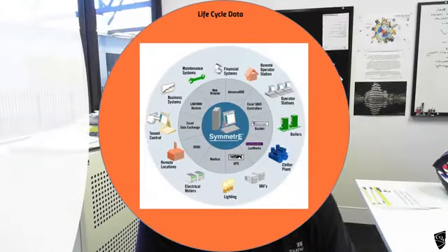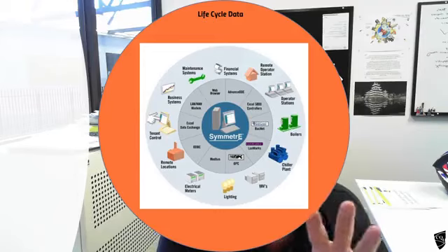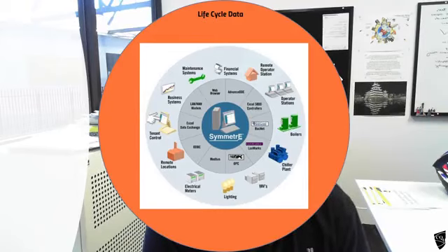Building management systems. Now this is what exists before building information management came along, and building information management is slowly absorbing these building management systems. But a building management system, it's got maintenance systems recording what needs doing and when it was done and who did it and how much. Financial systems, it can be operated remotely, so you can look at other sites. There's operator stations which might only be in the maintenance room or in the air conditioning room or in the building manager's office. And you can manage things like the boilers remotely, and they'll all be monitored, and your chiller plants all monitored and controlled that way.